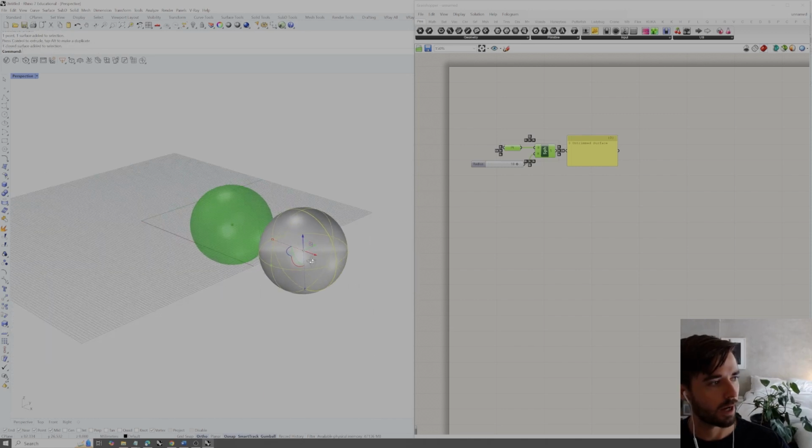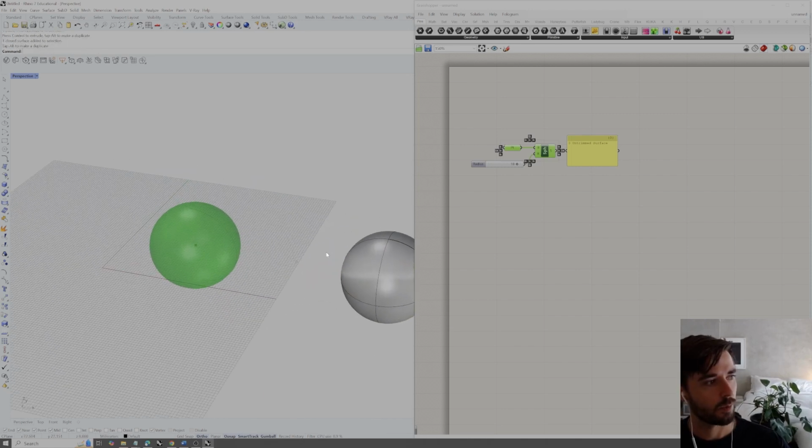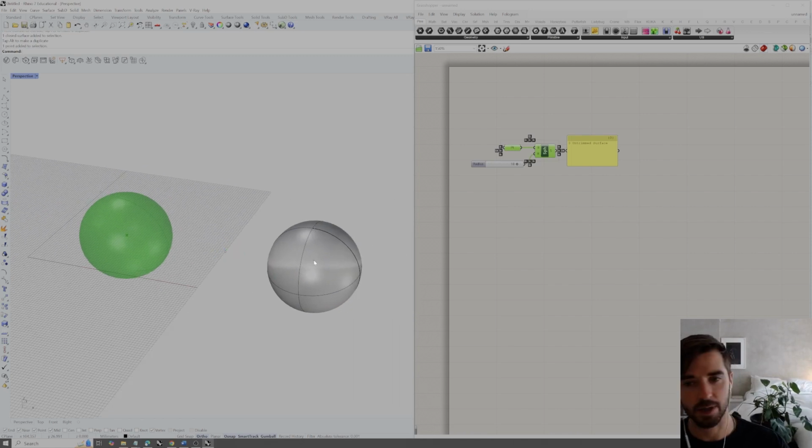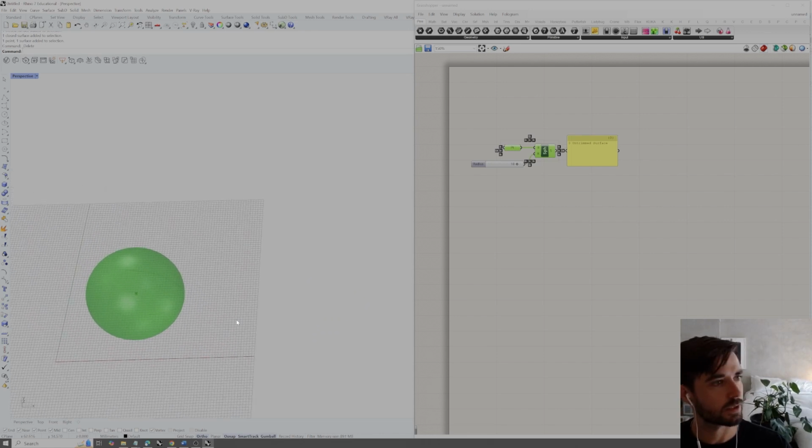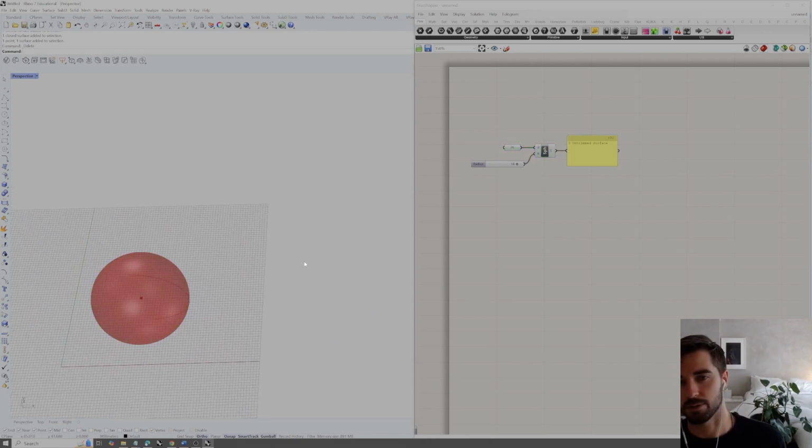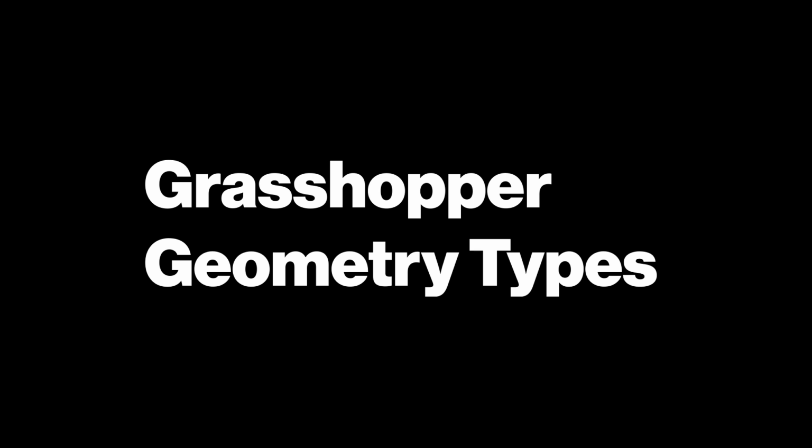So if I drag those out and then move this sphere, we can see that we had a point inside of that sphere, which was our reference point, but we rebaked it, so we still have that reference point, which is why that preview has not changed. Then we have the point that we actually baked over here, and then we have our baked sphere to its right. I'm going to go ahead and delete those, and now we're going to just step through a couple of different steps, mirroring some of the early exercises in the introduction to Rhino 3D.